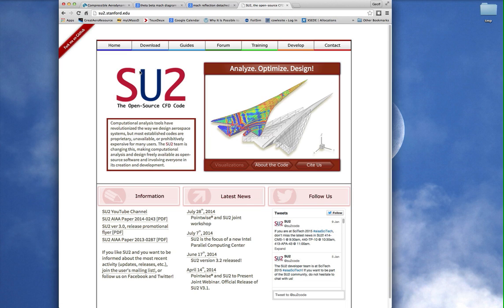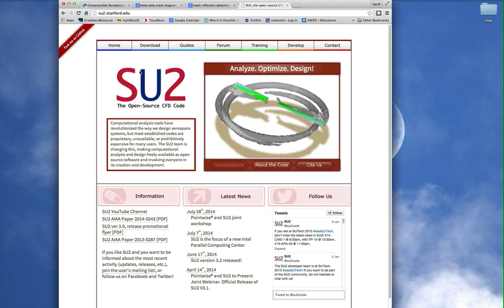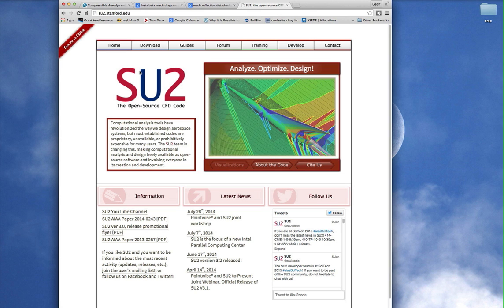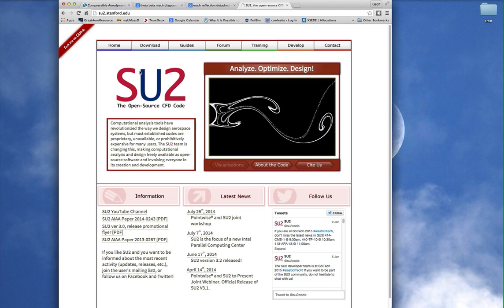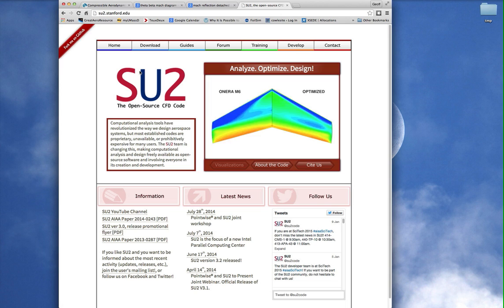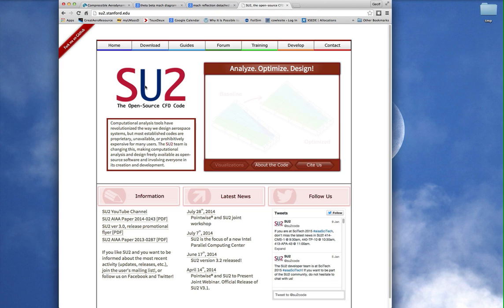It has built-in control theory based adjoint shape design, where the solver automatically computes the gradients of your cost function, for example drag, with respect to wing shape, and can modify the shape to find the best design within the constraints you give it. It's a pretty incredible piece of software that they've written in this object-oriented approach, SU2.